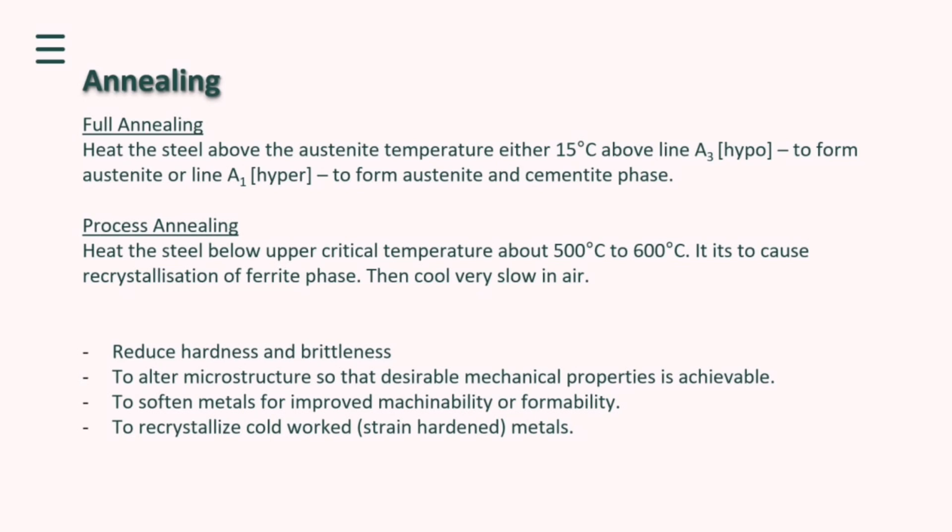So for annealing, the purpose is to reduce hardness and brittleness, to alter microstructures so that desirable mechanical properties are achievable, to soften metals to improve machinability or formability, and to recrystallize cold worked, strain hardened metals.